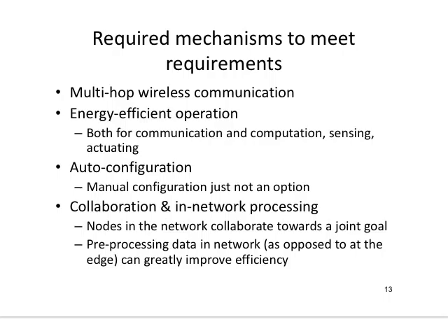So if I sense the temperature every 10 minutes and see that there is no change, then there is no point of measuring the temperature every 10 minutes. Automatically, I need to change this to maybe 1 hour or 2 hours. And if that's not changing, then I need to increase it more. So I need to do that intelligently without having some person or some human being to come and really do that on the sensor.